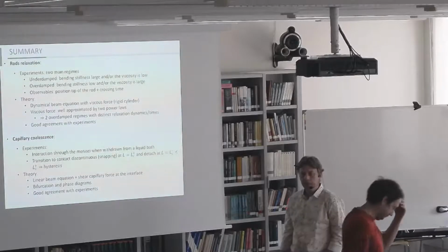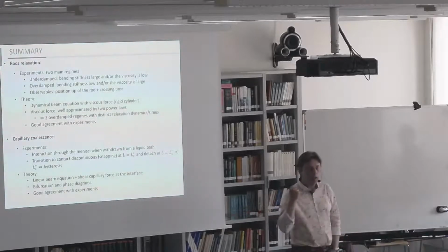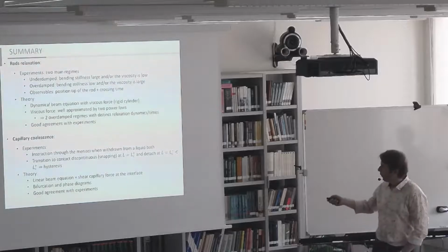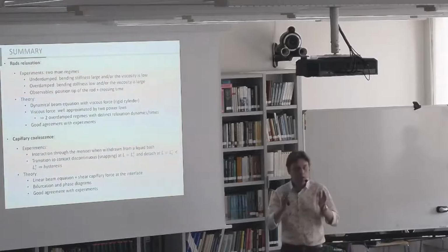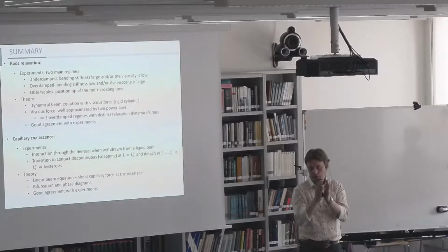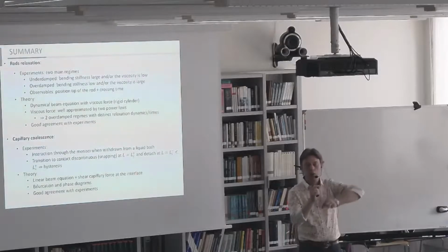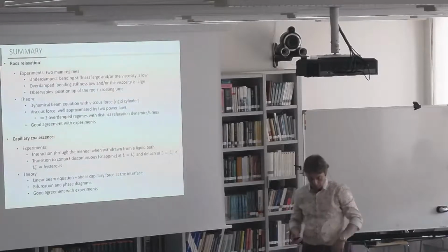Thank you. I was wondering if you can describe the hysteresis with your theory or with other. No. Well, this is a good question. So here with the theory, we can compute only L plus, but we cannot compute this one, and the reason is because of the approximation we did when we consider the force between straight structures. In this case, if the structures are straight, when they are in contact, then the contact zone extends over all the structure. And so we overestimate the capillary force.